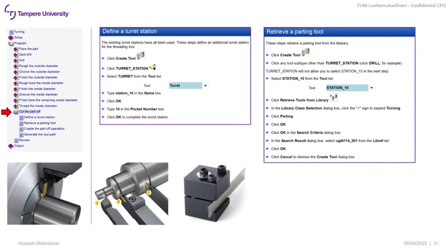And the cut of the part is basically the same thing that you are using with the same groove tool, except that now the holder should be in a way allowing you to go through the part. Depends on how big the diameter is, it might be possible to do or not. So for example, if you can see the groove number 1 and 2 here on the bottom, it is not allowing us to go through the whole part since the holder will be collapsing. However, on the left side, you can see that the tool is allowing us to do that, or even the number 3, or this specific one on the right hand side. So with these ones, we are able to cut off the part.